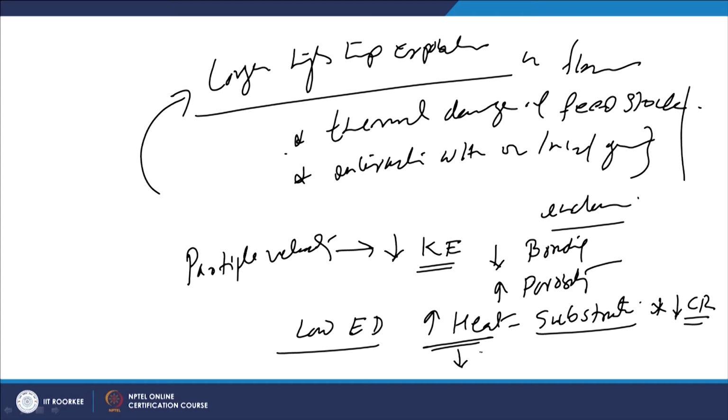So, reduction in the cooling rate of the flame spray coatings will lead to coarsening of the grain structure. This coarsening of the grain structure is an undesirable aspect. For the same material, we will be getting reduced and poorer mechanical properties.